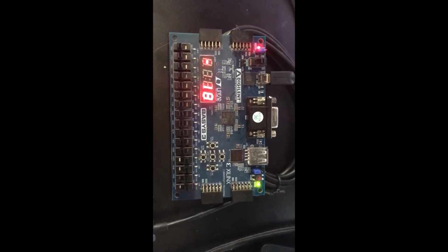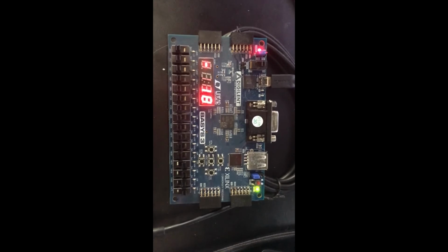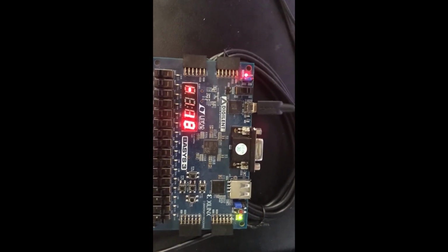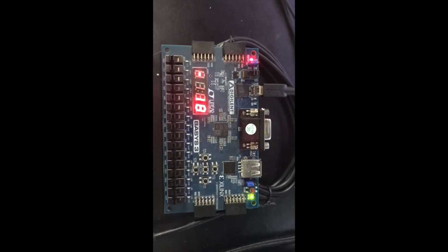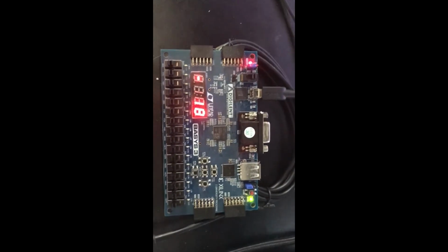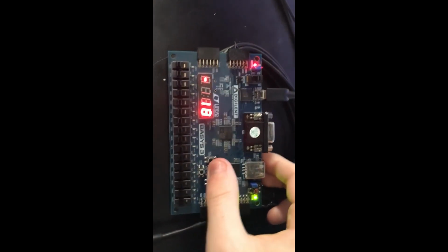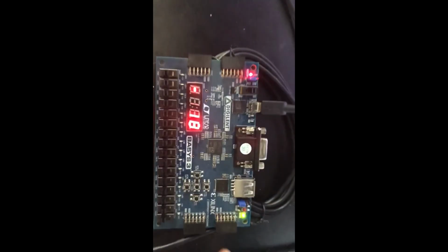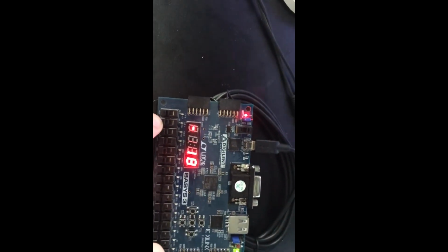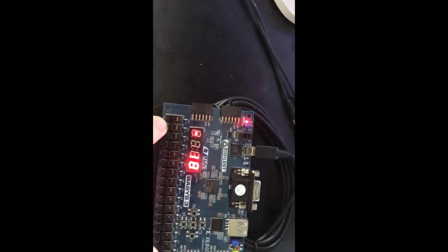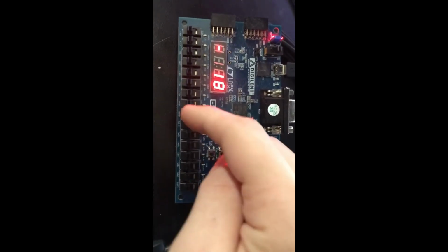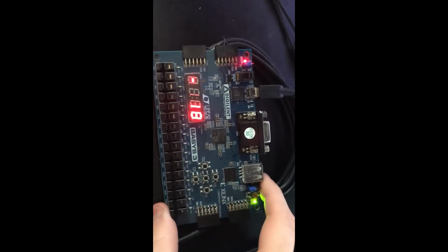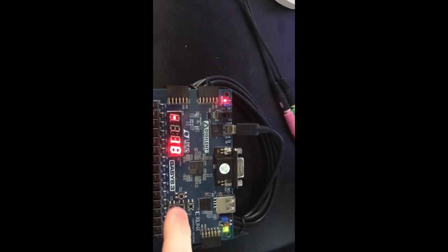Alright, this is the CPE Lab Final project demo. So, starting from the top, we'll test the zeros from Fahrenheit to Celsius conversion, Celsius to Fahrenheit. Right now we're in Fahrenheit to Celsius, as can be seen by the leftmost switch. This switch indicates the negative, if the input value will be negative, and the 8 switches from the right indicate your input value for temperature. So let's start it off.